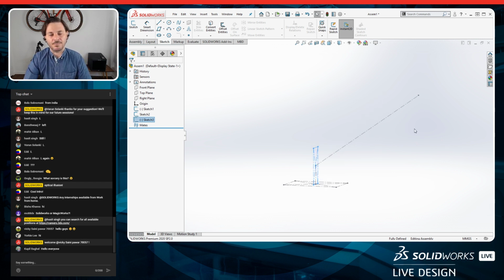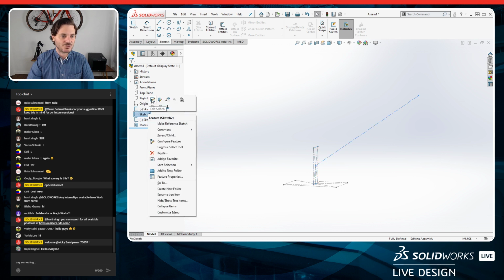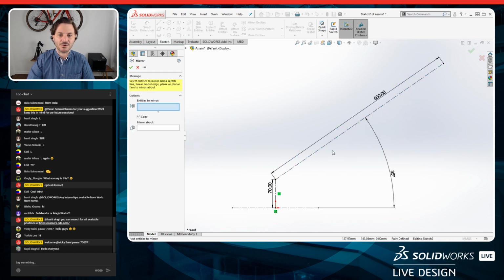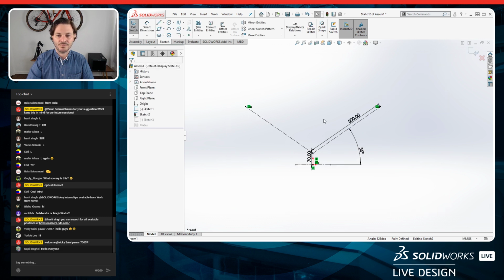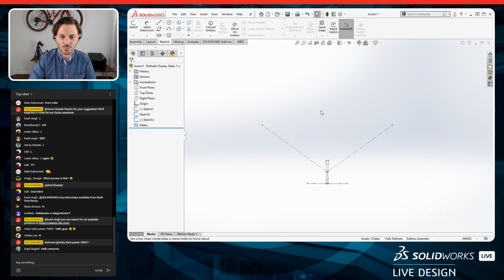So I forgot to do something because, as we know, the whole trick to this illusion is that you can see from one direction and the other direction look differently. So while I don't really want to spin my part around while I'm designing it, I should just create another view path going off in the mirrored direction of this line of sight. So I'll go back and edit my second sketch, and I'll simply mirror this line across my center line. Cool. Now that's easy.